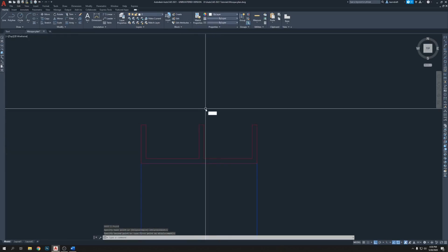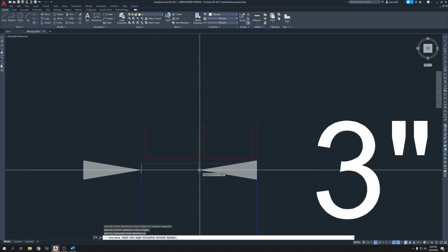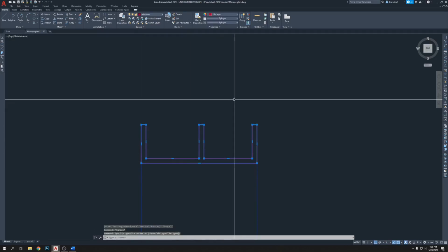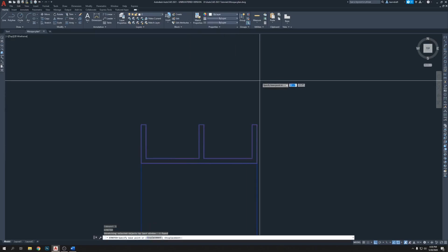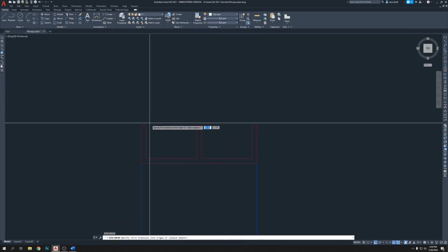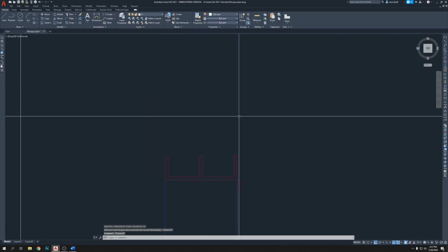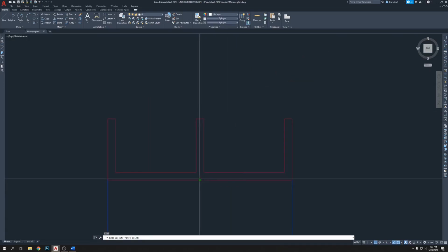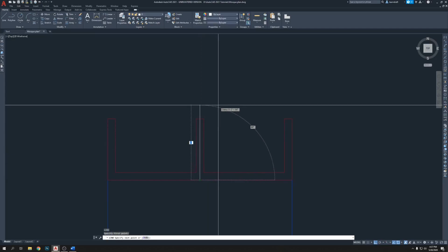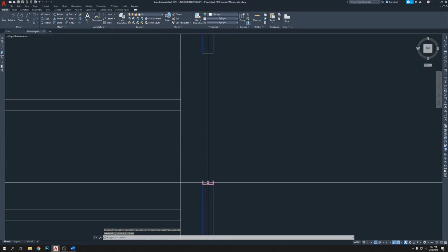I think no. Okay, so we need to stretch this one, stretch 0.125, which is 1/8 of an inch, and then try DLI, which is dimension style, and dim linear. So it's 3. It's actually better, we're gonna check just like this, not drawing a line, just check it. Okay, good. And let's delete this one because we fixed this one.